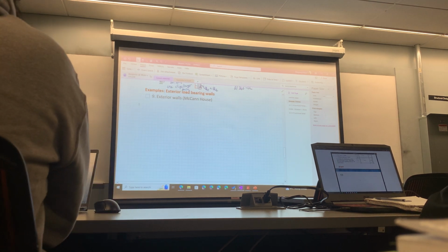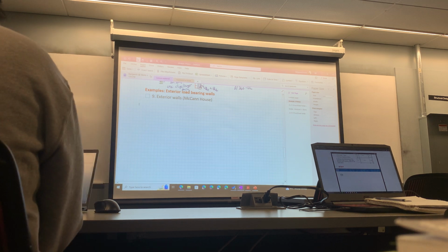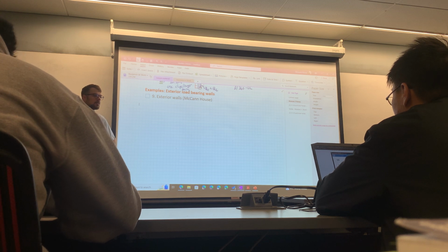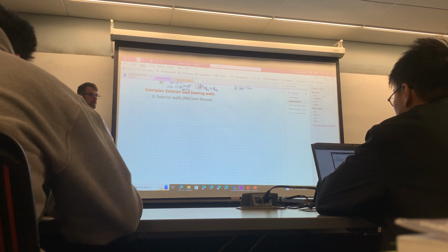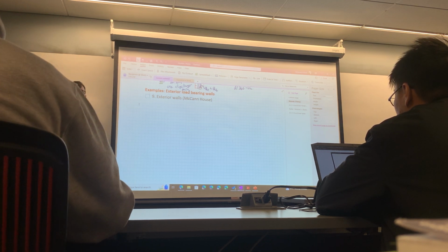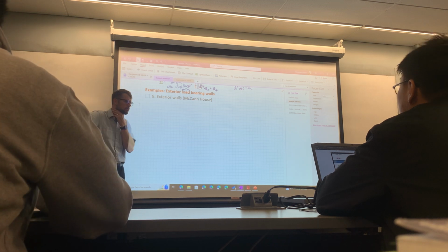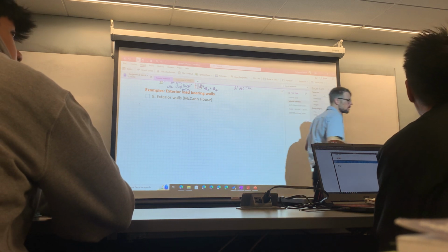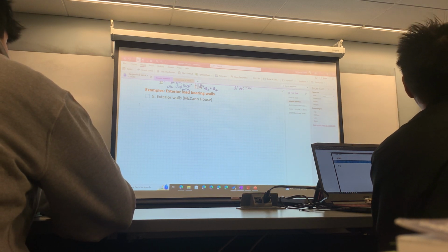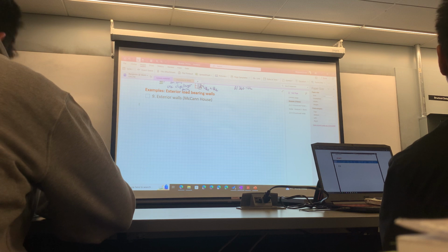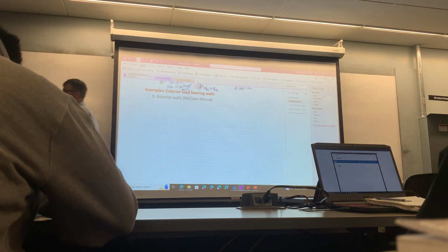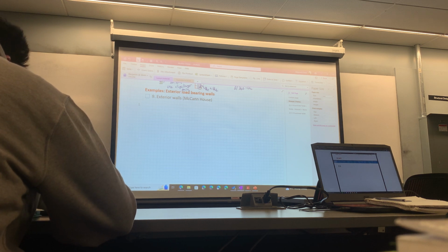Any questions so far on exterior walls? Is the concept pretty clear? Everybody can visualize what's going on here. Visualizing the failure modes is important. Are you guys talking about wood over there? Yeah. The failure modes are important to know because that's what we're checking for in our considerations, MR, VR. That's why I wrote it that way. VR is less than VF. MR is less than MF, because those are the considerations we're checking.